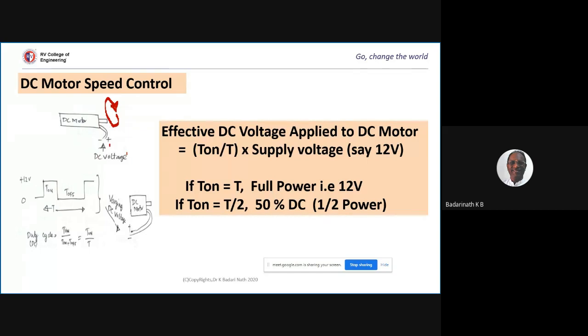Now, what is the only thing I can change for this motor? Immediately, I can replace plus and minus. Instead of minus plus, I can give the plus and minus this side. The moment I change the direction of the power supply, the motor starts rotating in the other direction. That means by reversing the polarity of the supply, I can change the direction of the motor, either clockwise or anti-clockwise.